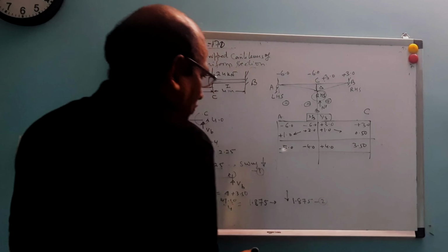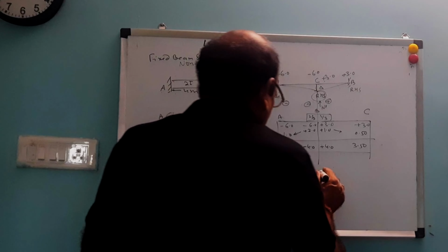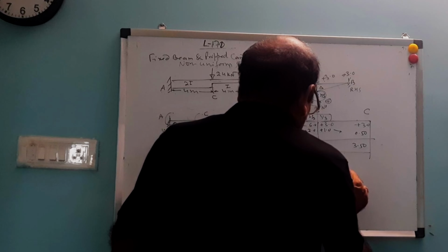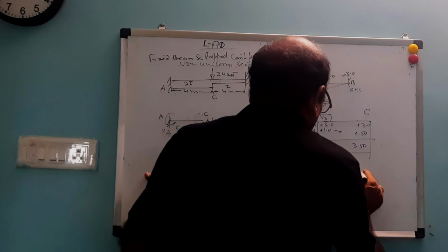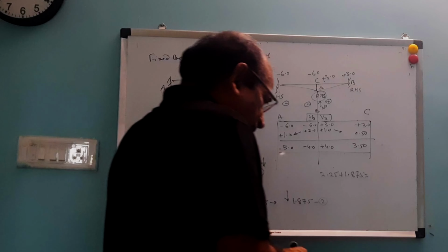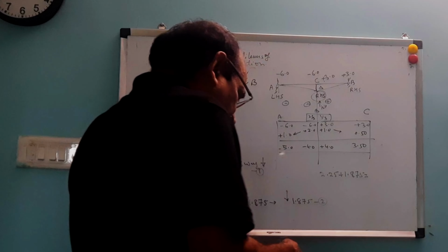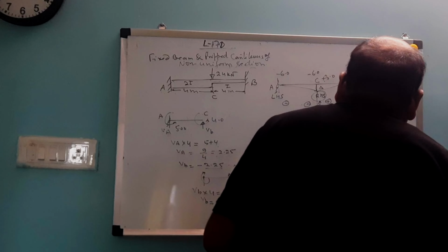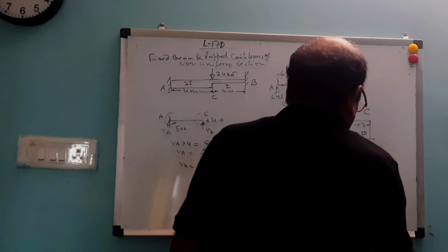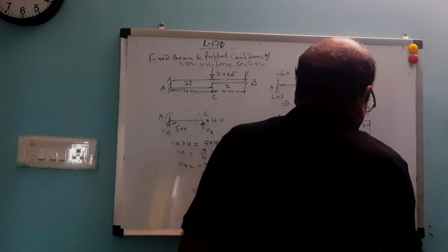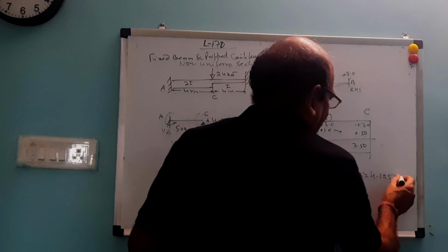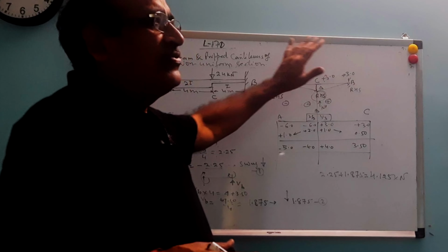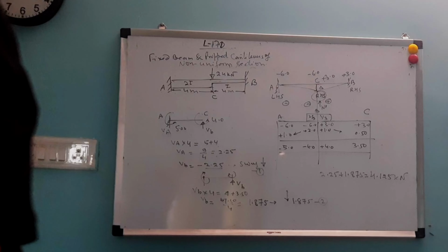So this is one sway and this is another. So what will be the total sway? That is, for both BB, that is 2.25 plus 1.875. You have to add both of these, plus 2.25. This is 4.125, right? Okay, this much of load is coming here to produce this much of moment at edges A and B.